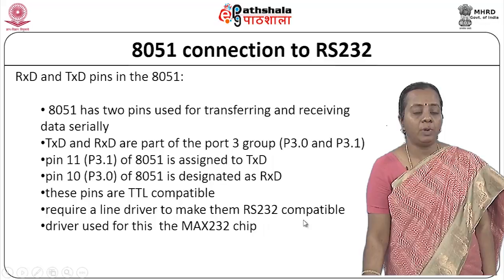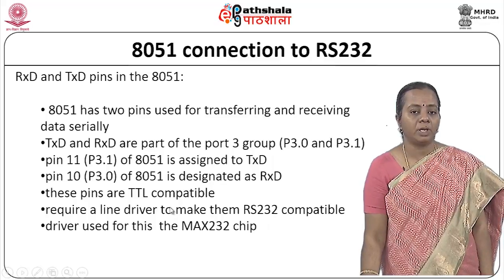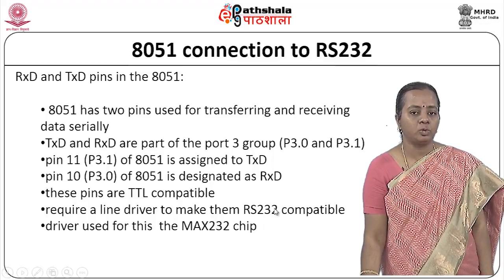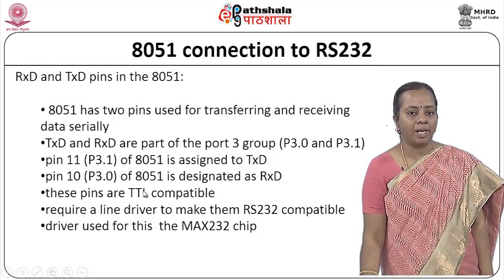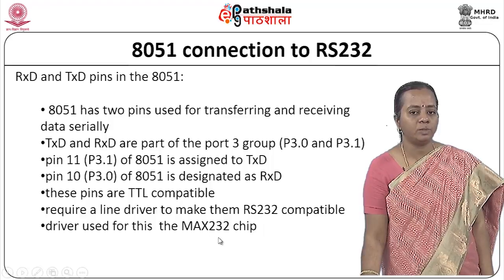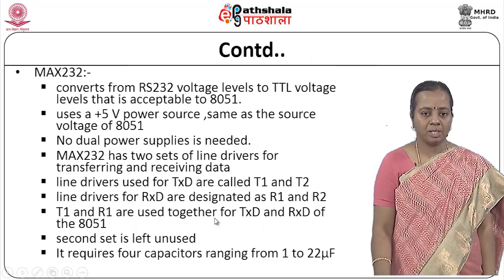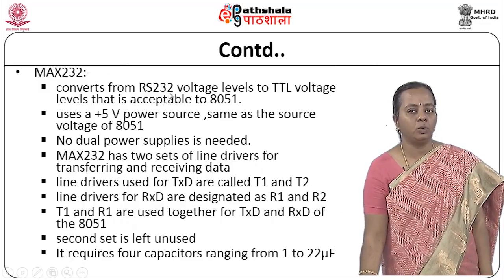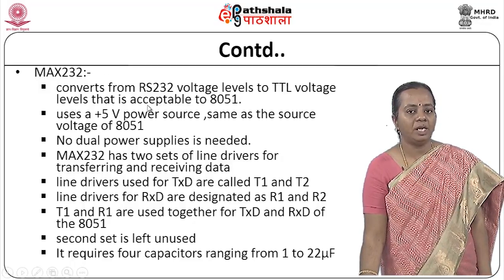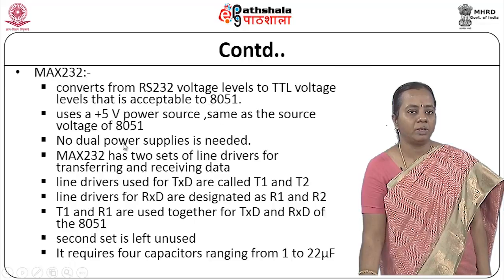And we need a line driver. That means we wanted to make RS232 compatible, so we need a line driver so that this is compatible. So the line driver here is specified as MAX 232 or MAX 233 chips. MAX 232 converts RS232 voltage levels to TTL voltage, which is acceptable by 8051.